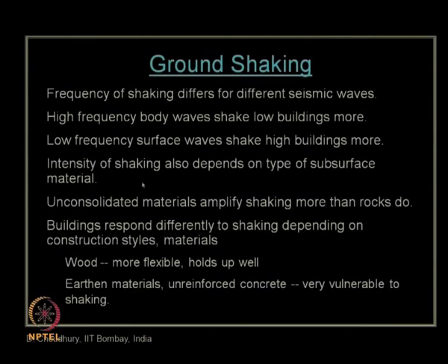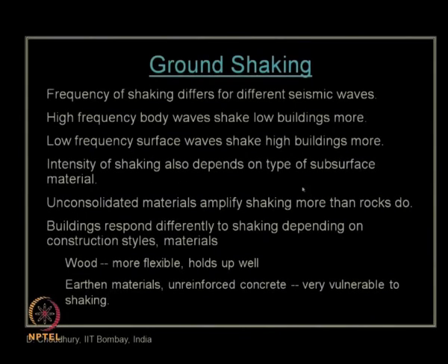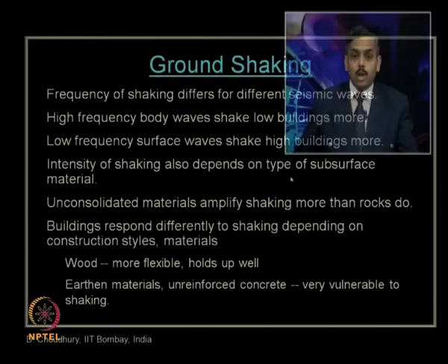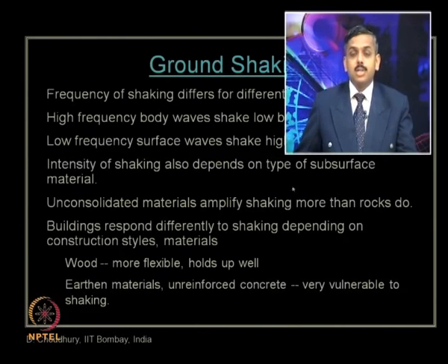Then the intensity of shaking also depends on the type of subsurface material, as I have just mentioned, whether it is soil or rock. If it is soil, whether it is a stiff soil or a soft soil, or in a loose condition or a dense condition, all these criteria will decide how much intensity of ground shaking is going to occur at a particular site.